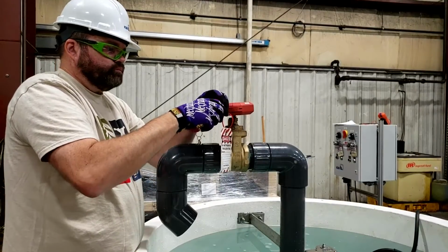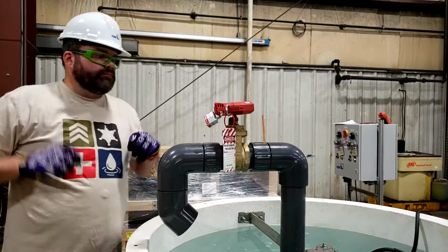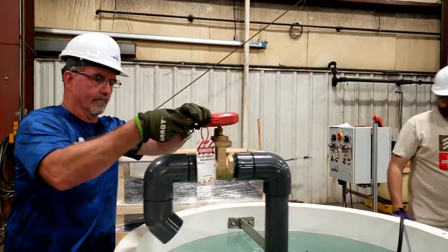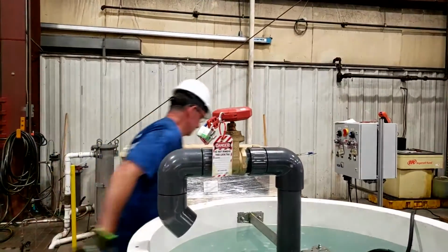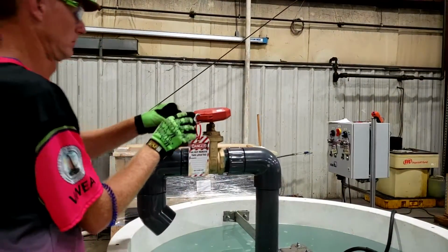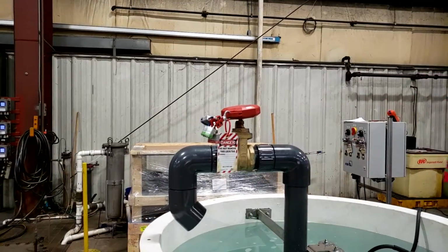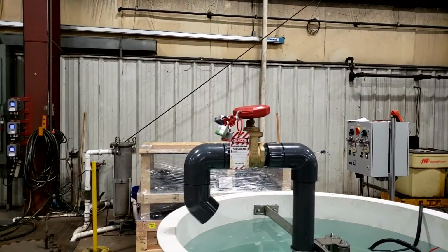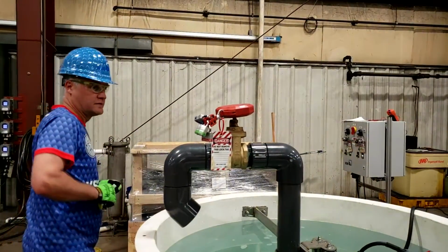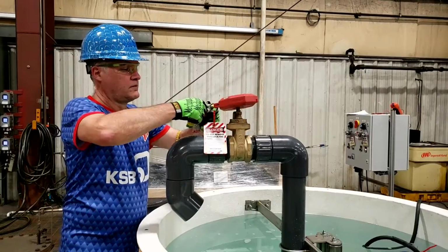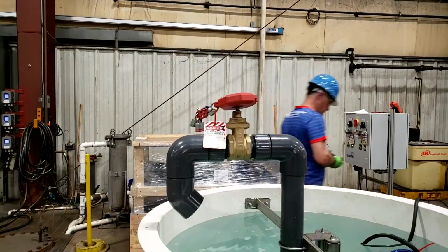Once you have closed the gate valve, you will verify that it is closed and communicate out loud that it is closed. After the safety supervisor lock has been installed, all remaining team members can lock out as necessary. While your locks are locked out during the event, your key must remain in your possession. Valves locked out.